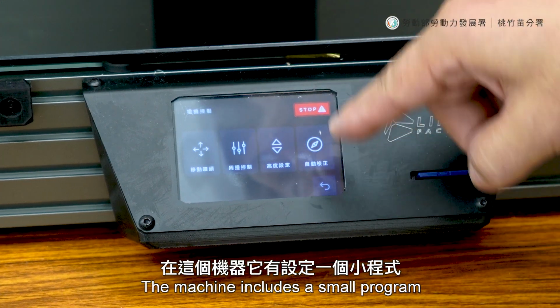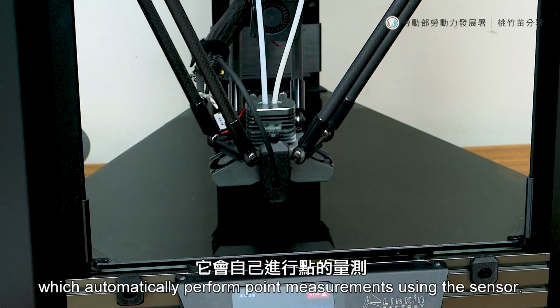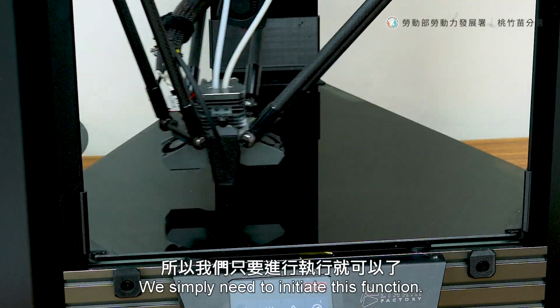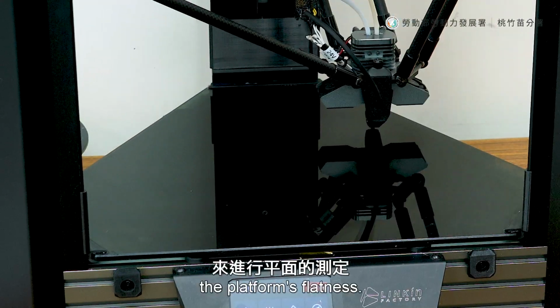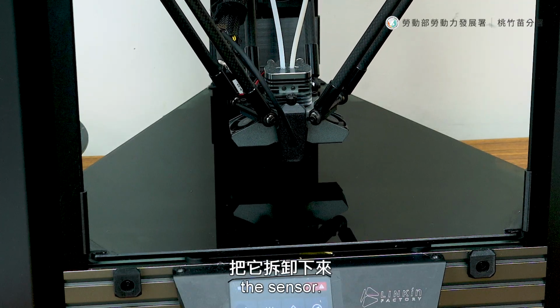The machine includes a small program which automatically performs point measurements using the sensor. We simply need to initiate this function. The sensor will use predefined levels to detect the platform's flatness. Once the calibration is completed, we remove the sensor.